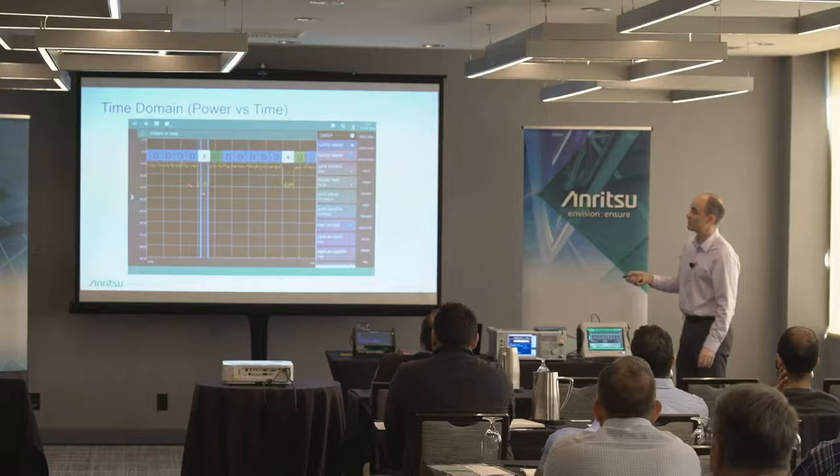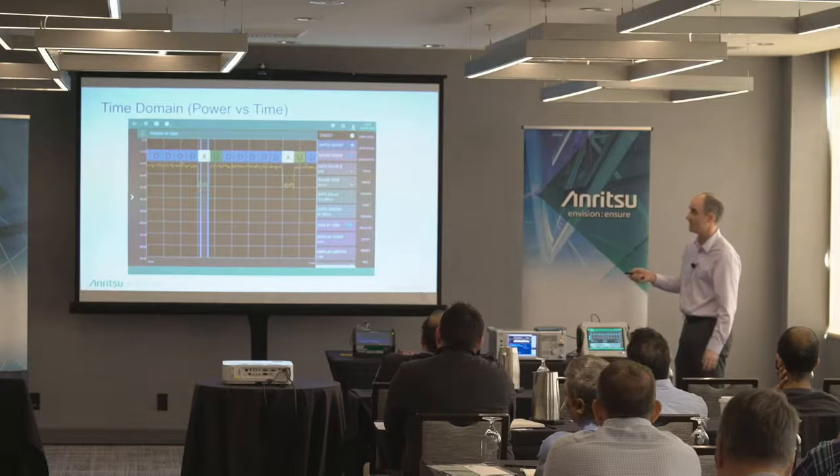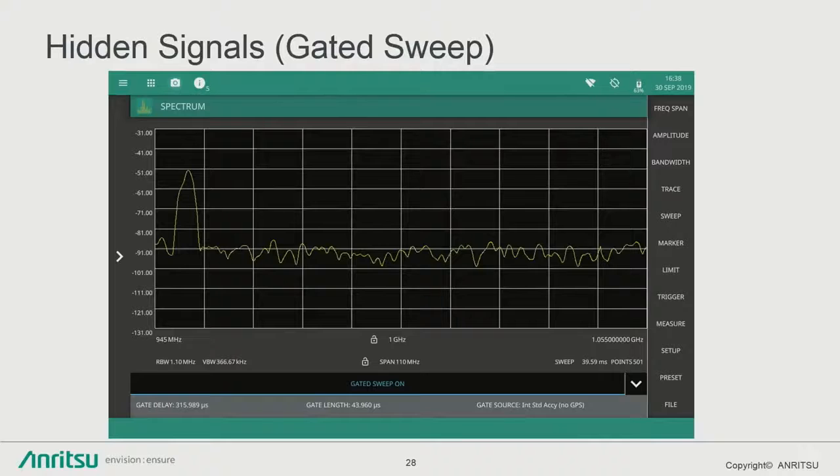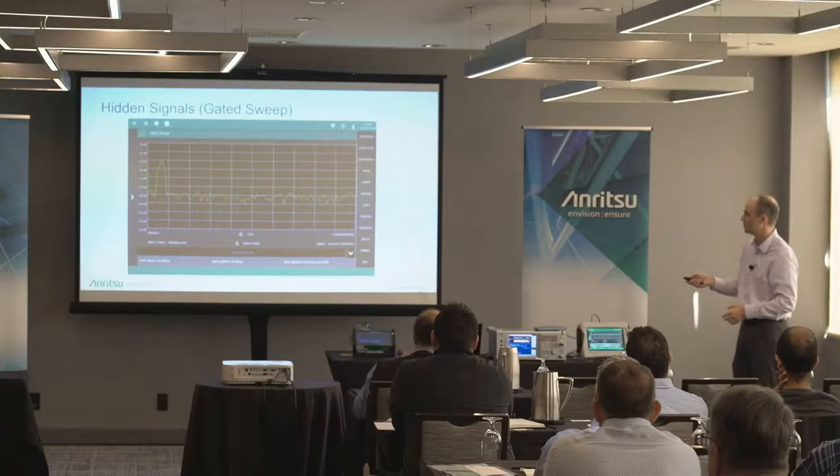So I go in and I look at this particular area where there's no activity, and what I actually see is that interfering signal on the side there. Okay? So I tell it, only show it to me when there shouldn't be anything there, and now I see it. Now, the other aspect to this is I'm still sweeping, right? This is not a video, but if this was intermittent, I would still see it bouncing in and out because I'm telling the spectrum analyzer, give me the gate when it's supposed to be off and show me whatever activity I have in that, what was the gates?